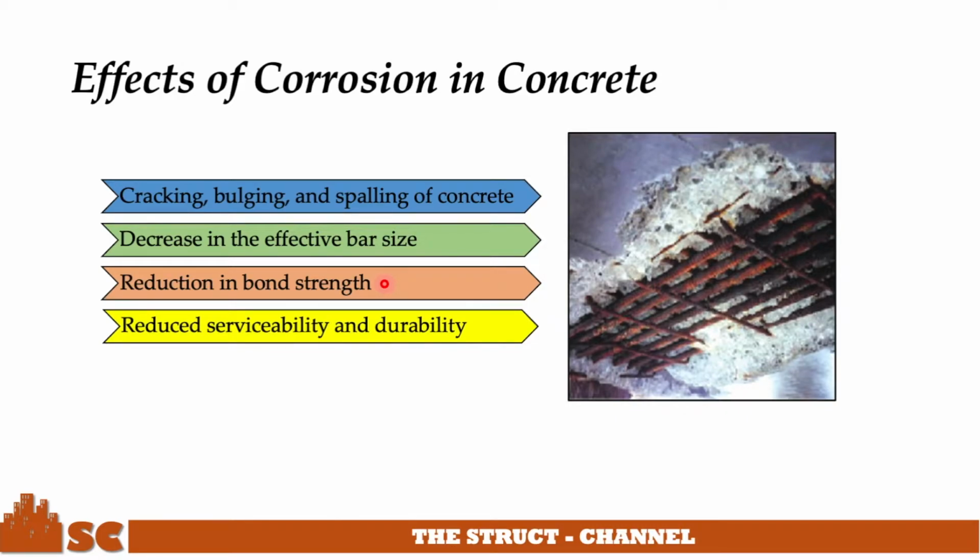The bond stress, in particular, balances the internal stress in the rebar through composite action of steel and concrete. When sufficient bond is developed, the rebar will not be pulled off from embedment and the reinforcement will reach the desired yield strength for ductile design. This controls the structural behavior of concrete under static and dynamic loadings.